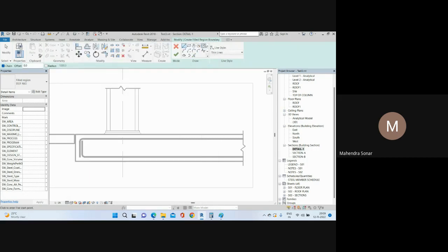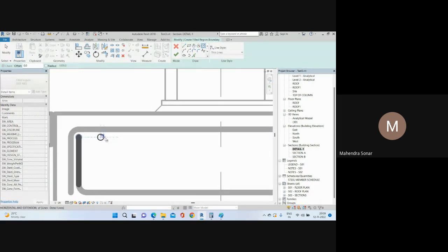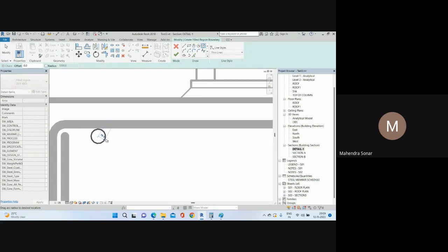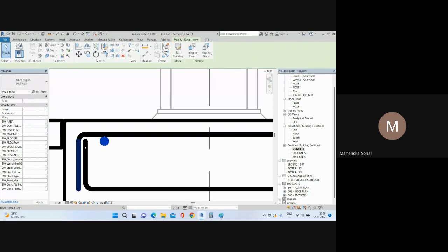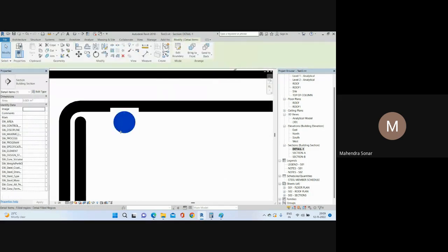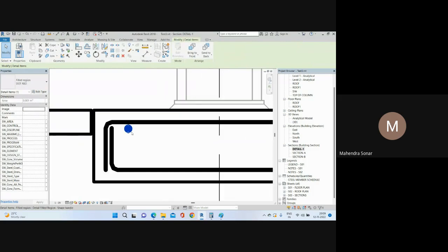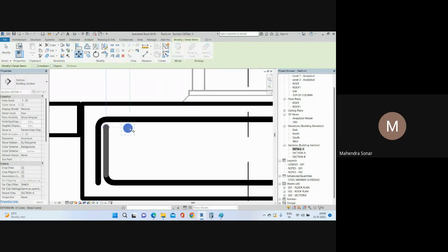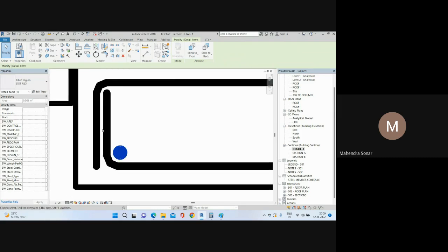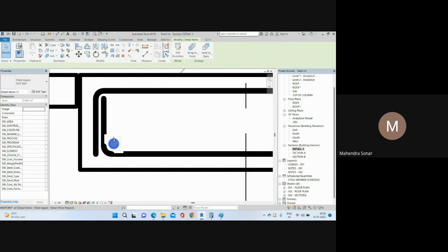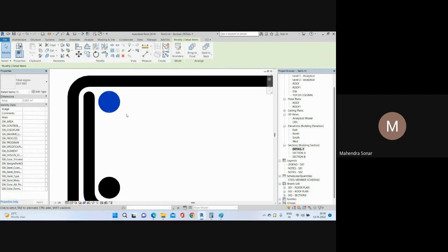Then after that you need to use this option circle, right? And suppose I want to just give 50 mm. You don't need to give the actual diameter, just indicatively. So I have given 15 radius and click OK. So you can see the donut has been created here, dot bar, right? Then after that you can just rearrange it. My donut first bar I want to move up, so it needs to be clear here. Then you can just copy and paste above and rearrange.